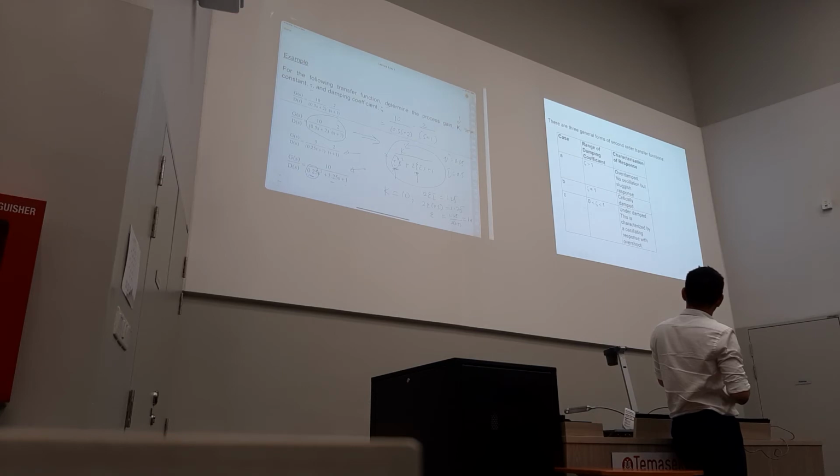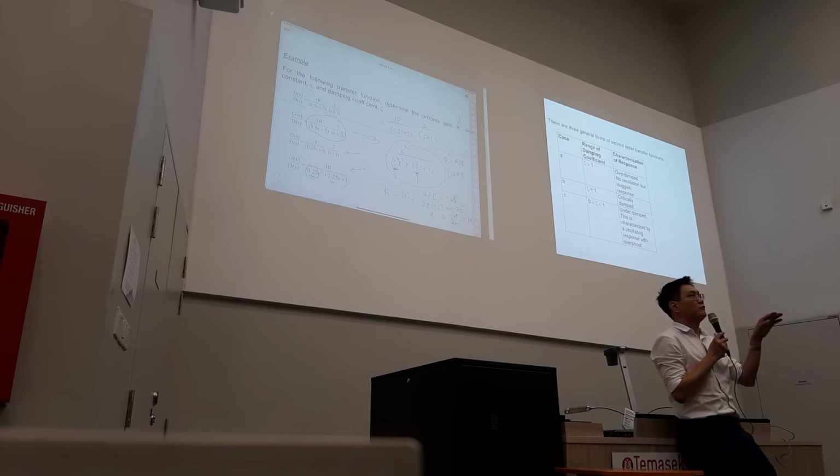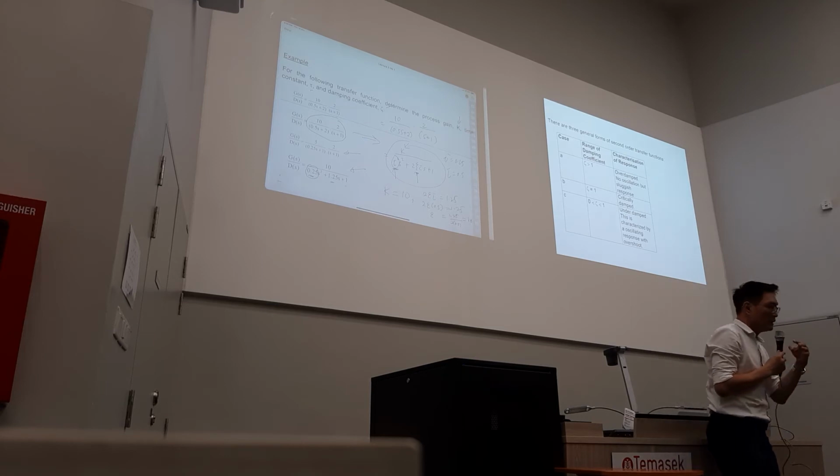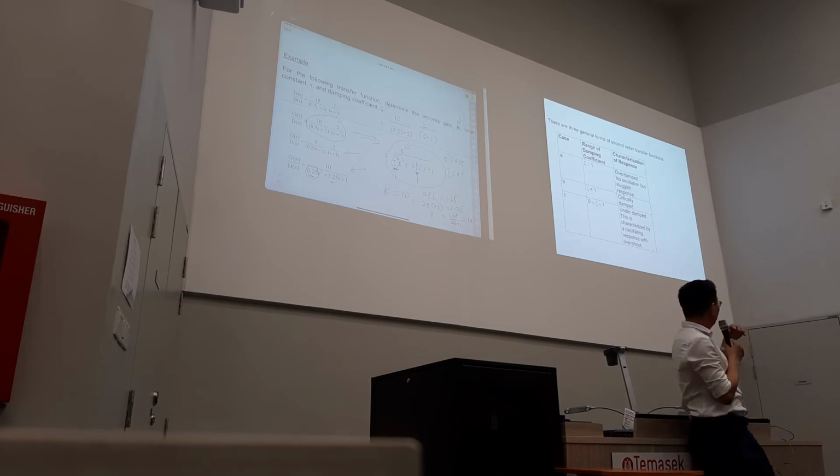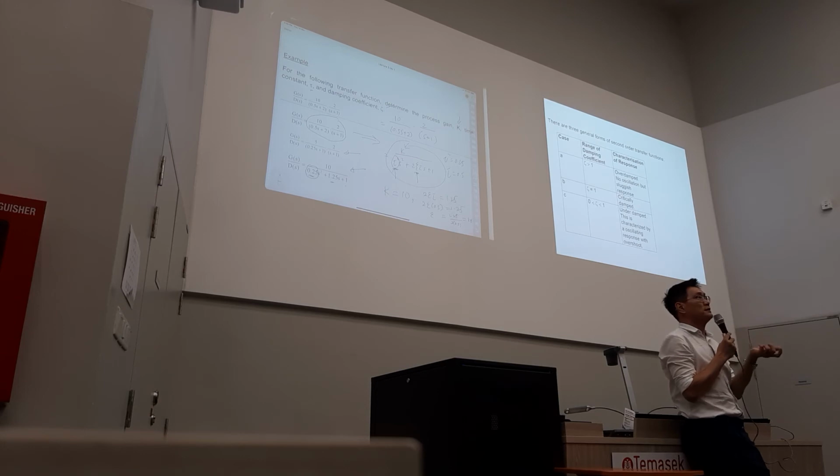But if I find that my damping coefficient is, let's say, for case B, the damping coefficient is equal to 1, which is critically damped, which means that it's very fast. The response is almost immediate after you change it, it will go back to the original output after a very short period of time. So cases like that mean the process responds very fast.